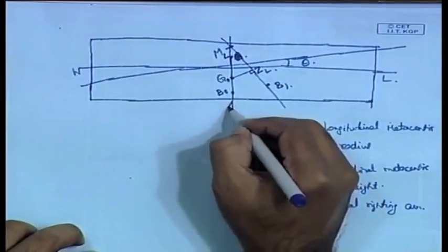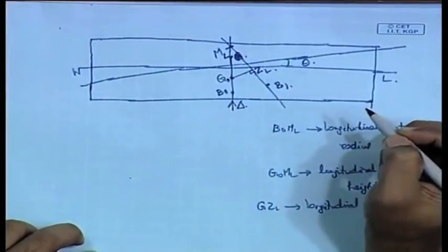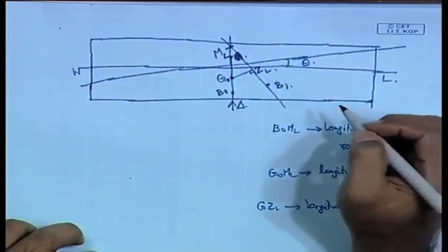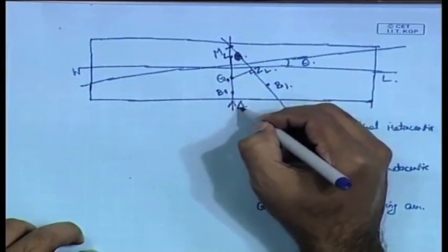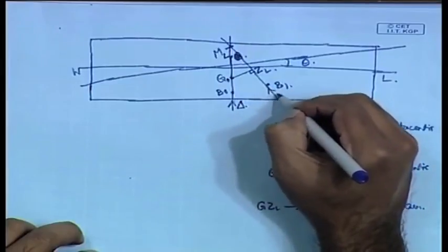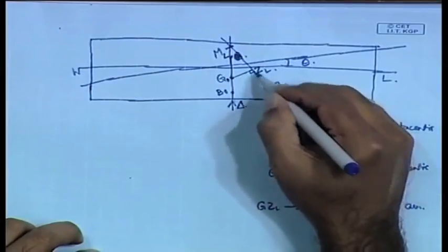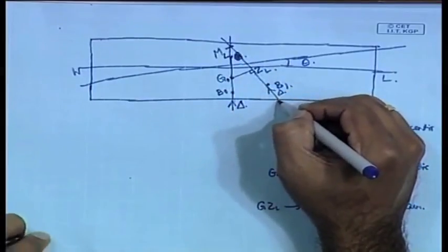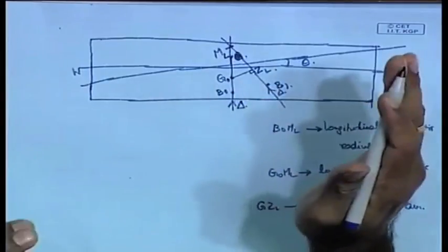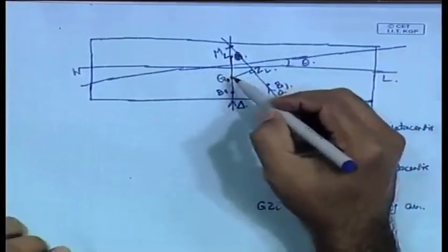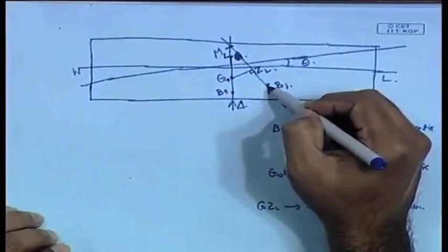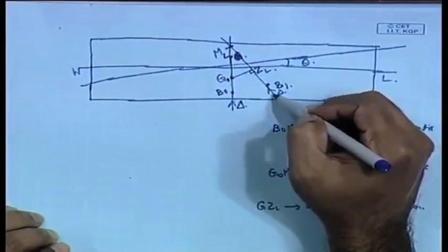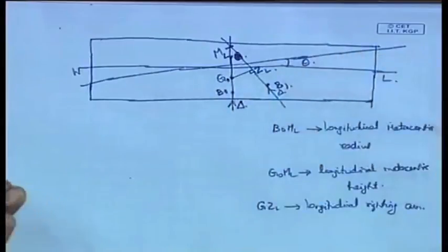And therefore, here at B0, through this initial vertical there is a force delta acting. So, here you have the weight delta, and in the final state, that is when the ship is trimmed, you have the center of buoyancy here, and through that center of buoyancy acts a force delta, that is the weight of the ship, because the ship is floating.